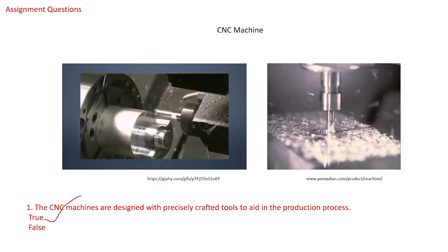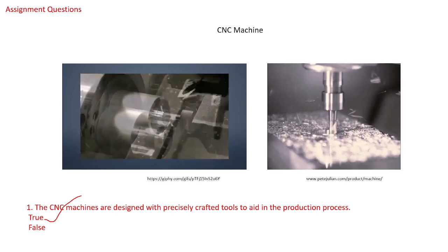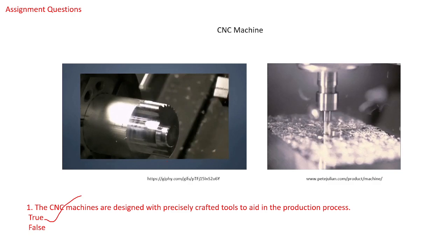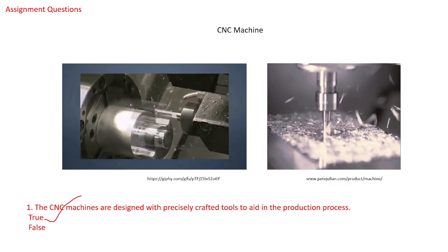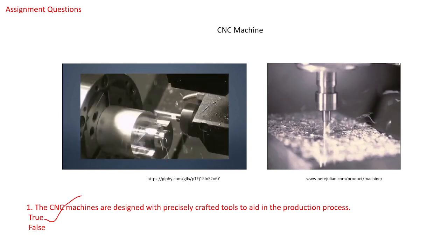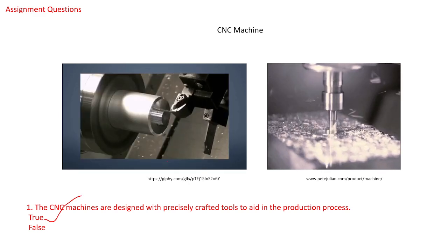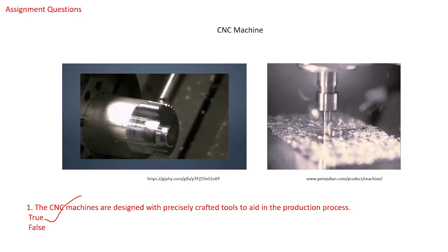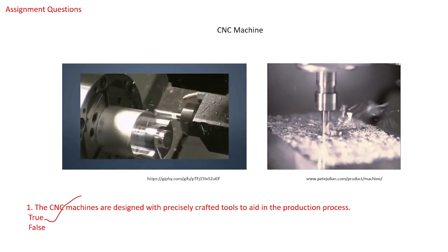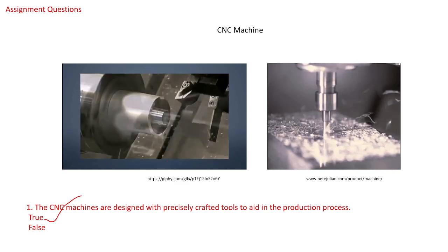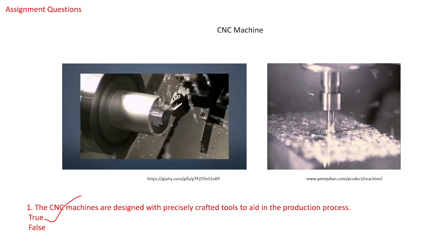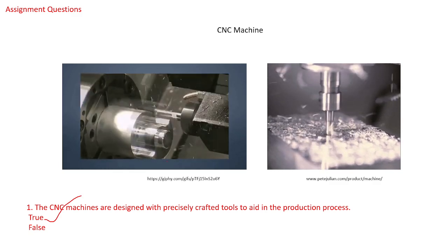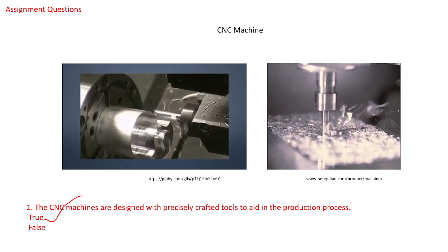Rotating components will always have a much tighter accuracy because otherwise they will give imbalance. It also depends on the type of matching. If you have another matching or joining component, this tolerance matters very much in the joining. Based on the component drawing, we have to select the machines, whether we have those machines or have to outsource. All those decisions have to be taken.